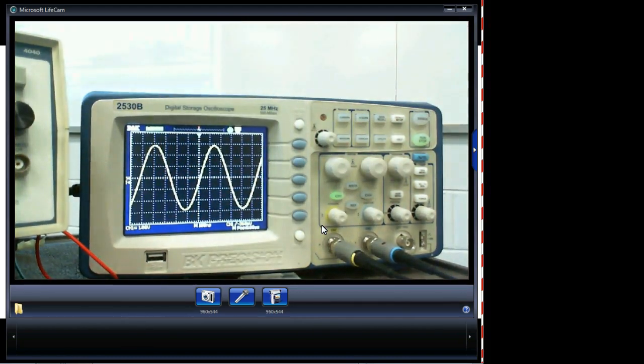Also, even troubleshooting power supplies, which is the first thing we're going to get into, you can't hardly troubleshoot a power supply without an oscilloscope. Sometimes you can, because there are certain things that happen, and by looking at the waveform, you can tell what component fails. Usually just by looking at the output of the power supply, you know what's failed inside right off the bat. We have some analog scopes in there, but once you learn how to use one oscilloscope, they're all basically the same.